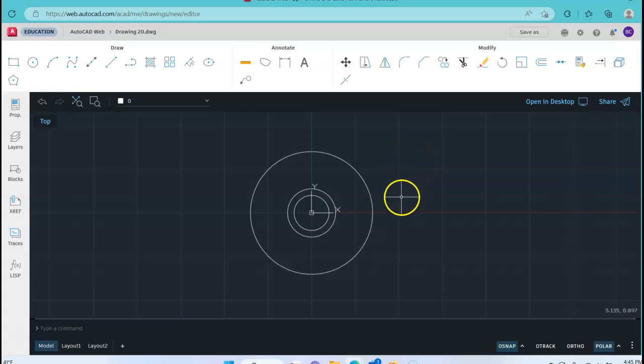Now, notice I also have 3 holes here. If you look at these holes, you know the positional coordinates for one. Which one do you know positional coordinates for? Well, if you look, there is a center line, and the dimension on the center line given to you is a 5-inch diameter. That's what we call a bolt circle.